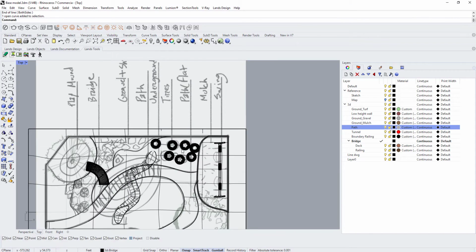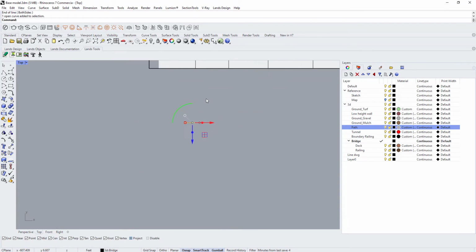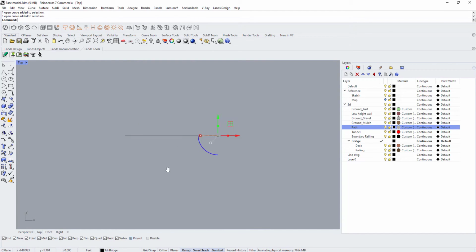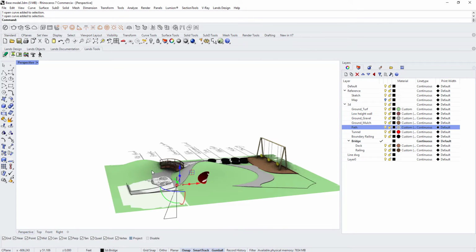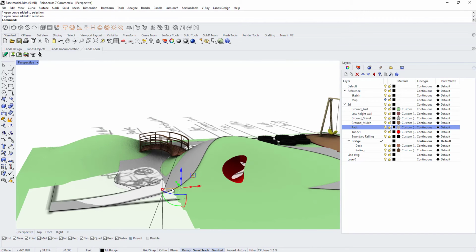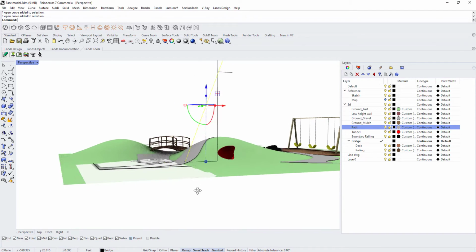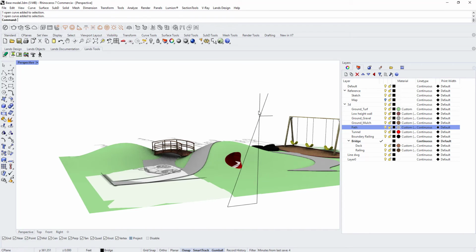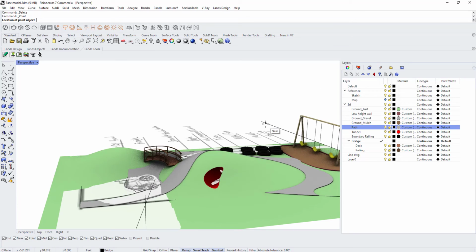Now I'll go to the top view and rotate that line while copying it. You can do that quite easily. So I'll also try to create a point in that intersection for my own reference. So I'll go to the point and I will remove the project snapping and create a point right there.